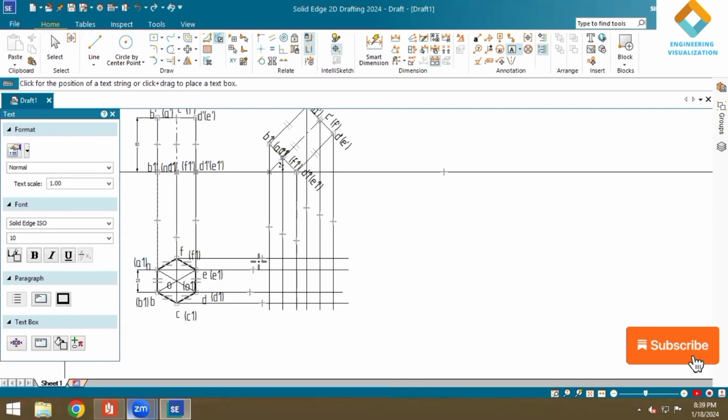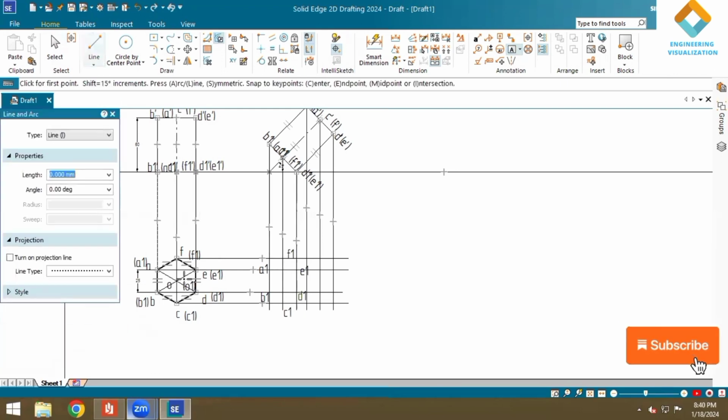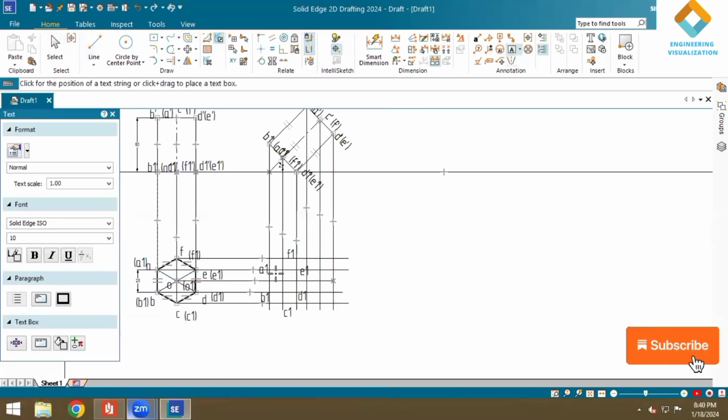Write the notation for the top view. In the top view, the bottom face is A1 B1 C1, like that you can write down. Draw a projection line from O also. This is O1. In the same way for the top face, you can write down A B C D.